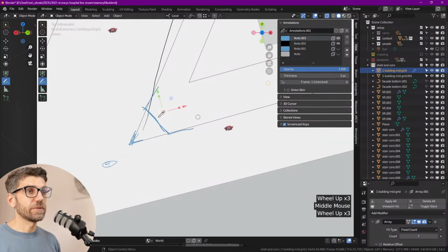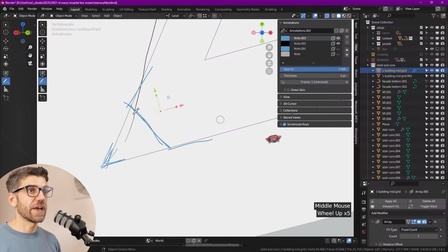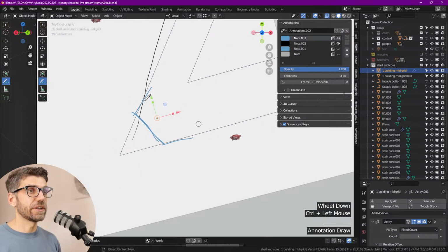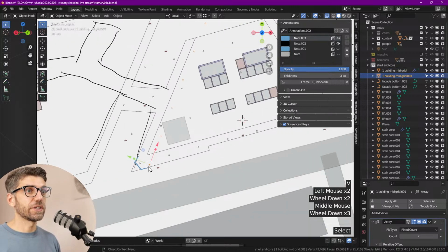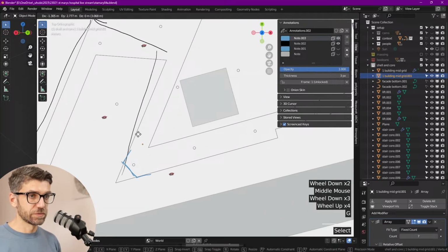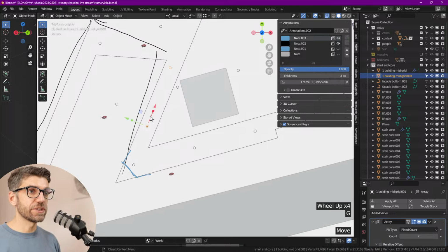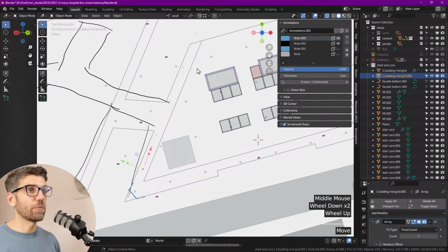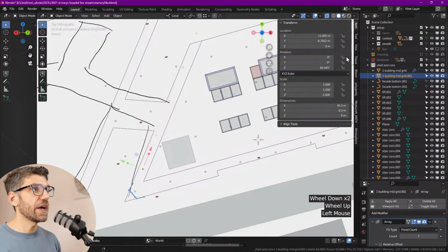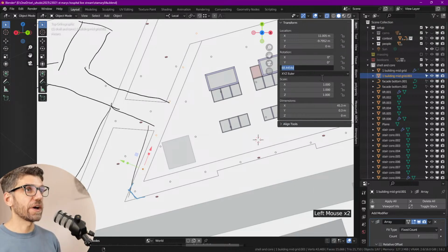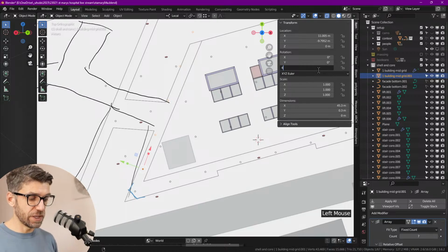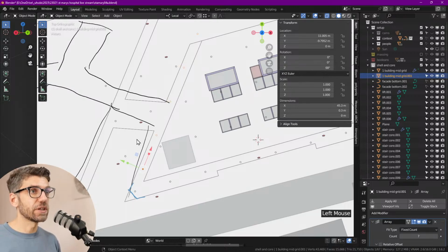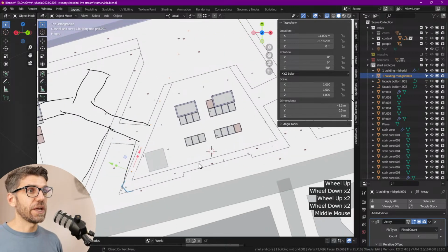Okay, and that column actually lands pretty well if we have this kind of corner setback, doesn't it? So that's one thing. Now let's think about the other columns. They should be more or less aligned with this edge over here, with a 1.5 meter setback. What is the angle of this? I'm curious. 68.455. I'm just thinking we can probably make this a little bit nicer, so let's try 70. Or it should go the other way, so 68 degrees. Okay, that's working pretty well. So that's more or less the grid, isn't it?